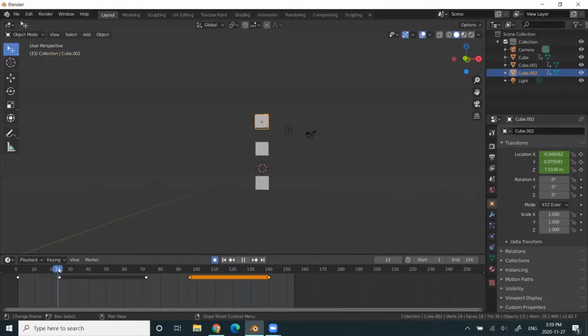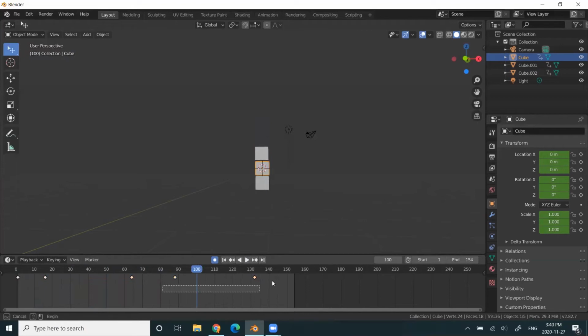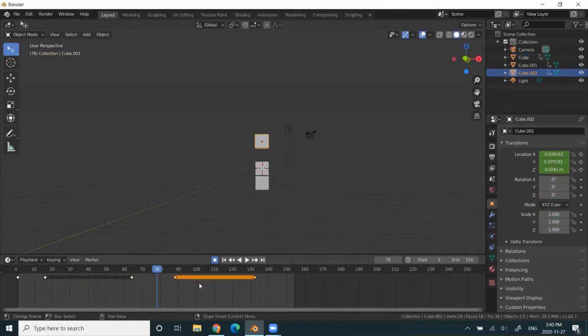Now you can change the timing of this. If you feel like this is too slow, then all you need to do is move these keyframes closer to each other, which means there's less time for the keyframes to travel that distance to the two different poses that you set. And you want to make sure it's consistent with the other parts of the object. So if I only moved the keyframes for this top object down starting from 16, I want to make sure that I do the same thing to this other part here. Okay, so now the object gets pulled apart a little bit quicker, and I can also move this closer to each other here as well, so they can come back faster.